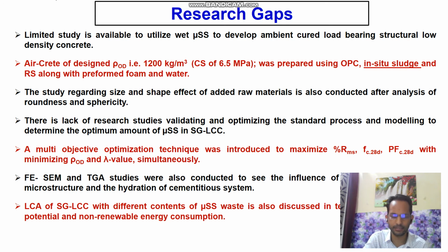The in situ sludge was collected at the site and transferred to the production site of lightweight concrete, along with river sand, and of course preformed foam of desirable density as per IS 2185 part 4 and ASTM C796, and water.